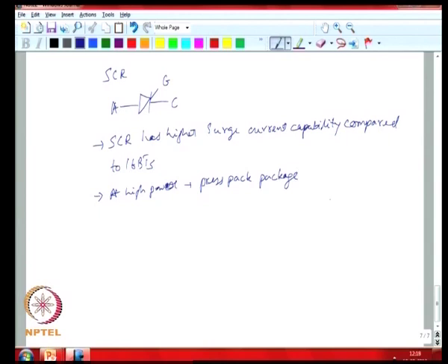devices. So, PressPack package is essentially like a cylindrical plate, and essentially one side would be your anode, the other side would be your cathode, and you would have leads for gate and cathode coming in from the side.